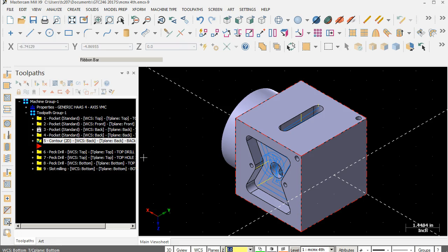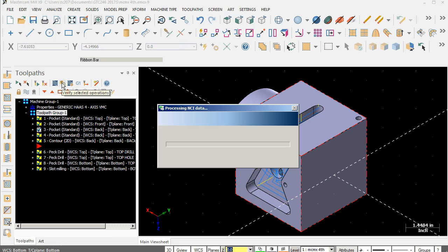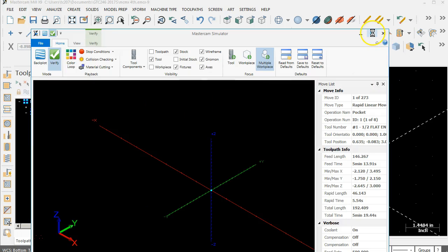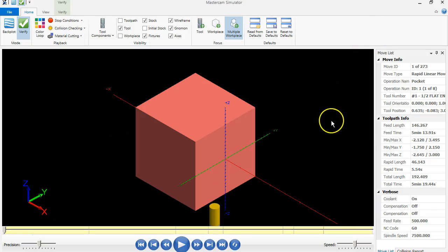Save often, save oftener. It always goes quicker the second time around. We just don't like second times around. All right, so let's go ahead with the toolpath and set up for the verify. What I'm looking for in the verify, maybe not even so much for the pecking drills, is just looking for that order of operations and setting the direction.